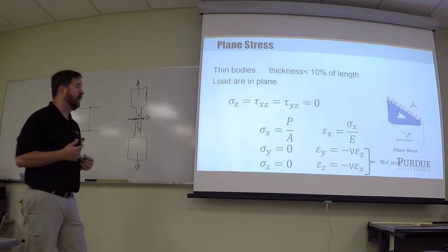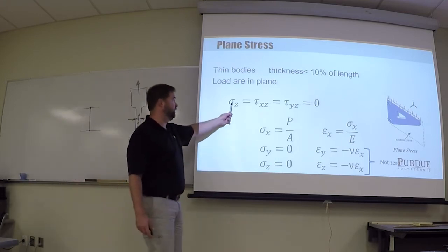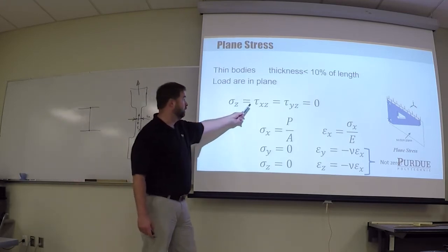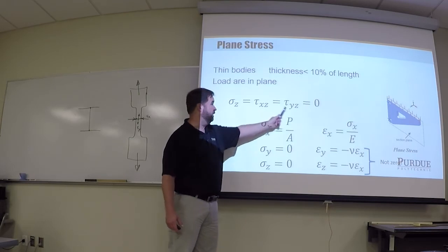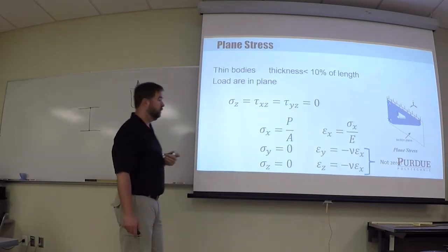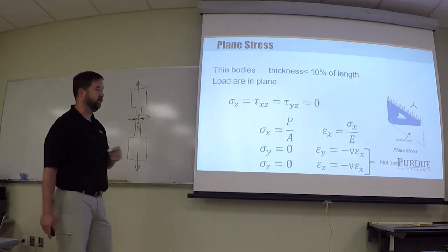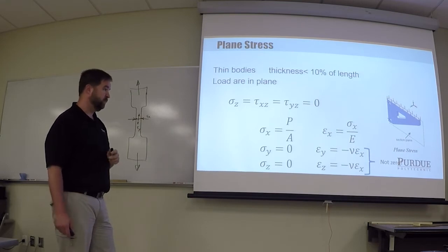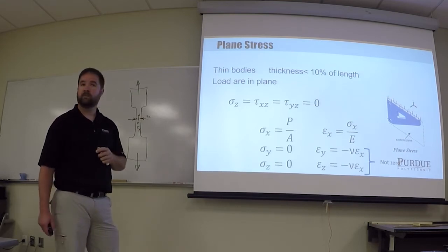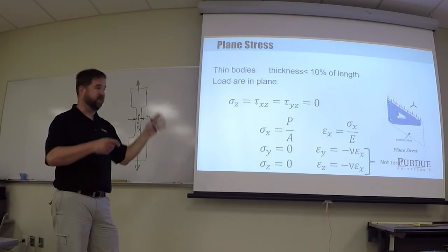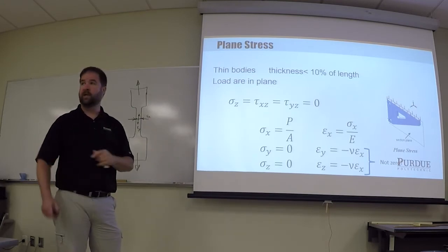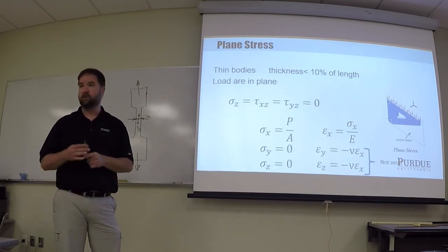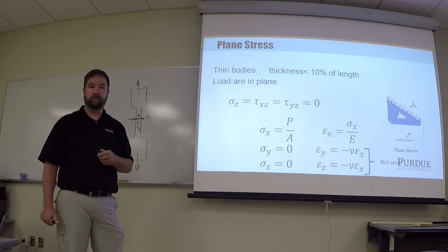When I do all of that, I assume that the stress in the z direction is 0, and the shear stresses that are associated with the z direction are 0. And when I do that, then my equations become simpler, and all of this gets worked into the formulation that SolidWorks is going to use in order to solve these models for you. Okay?